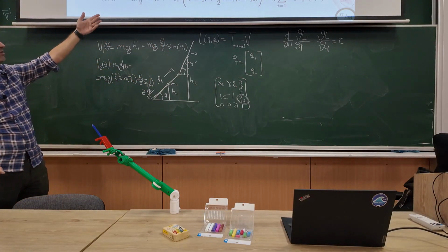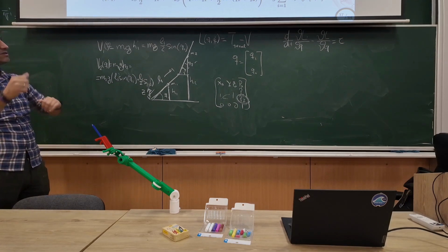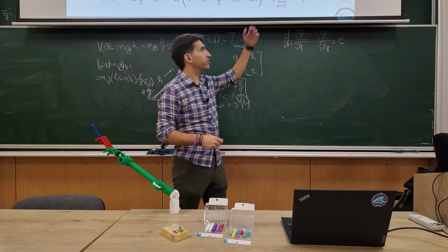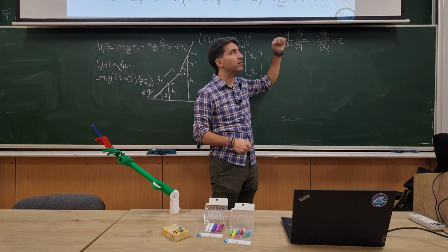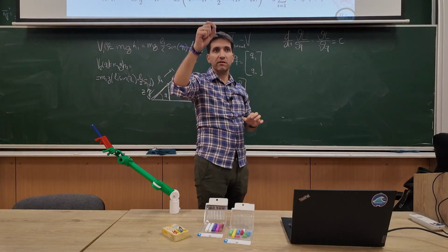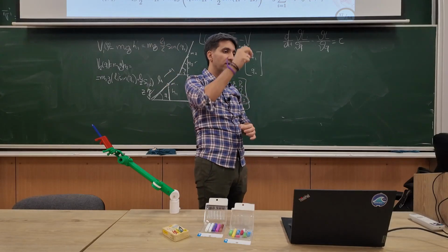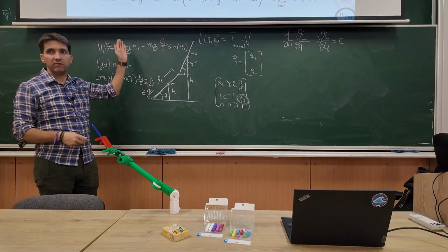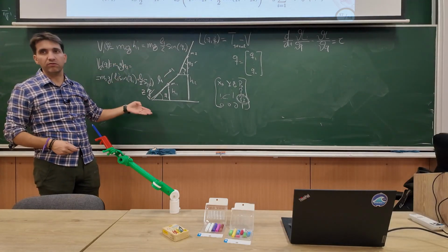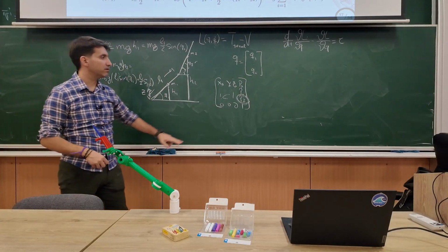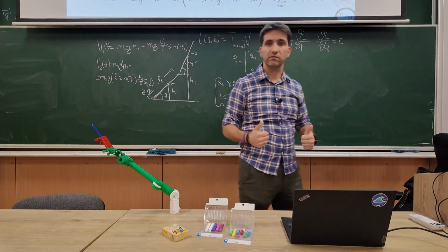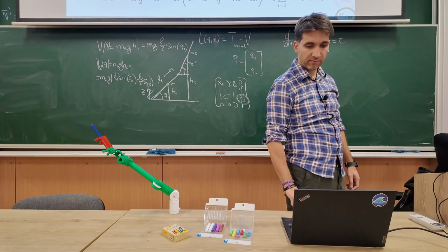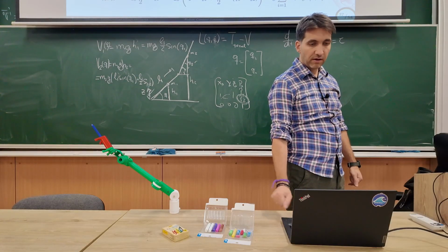Because here, this will depend on the design of the robot, how the axes are rotated. But I can calculate it for any robot if I know the forward kinematics, which we know how to calculate by taking the forward kinematics until the center of masses, and then taking the coordinate along the gravity direction. Typically, we put Z pointing upwards, so this would be this element, all right? So in the general way, it's like this. Clear?